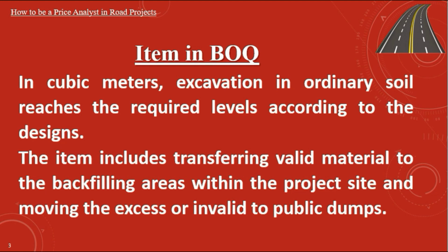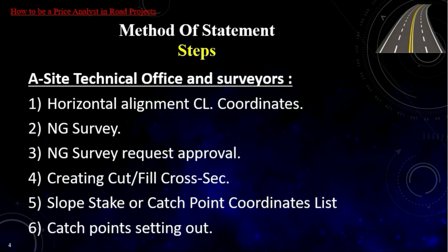In cubic meters, excavation in ordinary soil reaches the required levels according to the designs. The item includes transferring valid material to the backfilling areas within the project site and moving the excess or invalid material to public dumps. Site Technical Office and Surveyors.